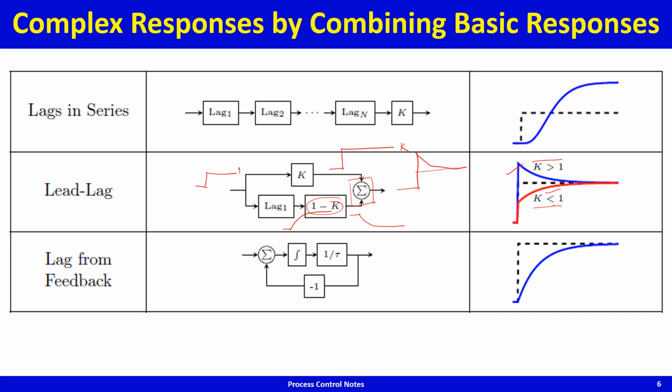So this is a parallel structure which gives a parallel lead lag kind of structure, where the basic dynamic elements are being combined in parallel. In nature, most things happen in parallel. So series structures are there, parallel structures are much more common. You could also have the basic dynamic elements combined in a recycle structure, in a feedback structure.